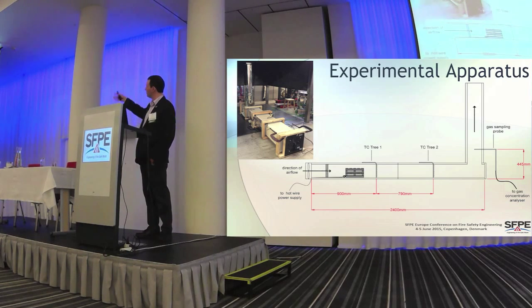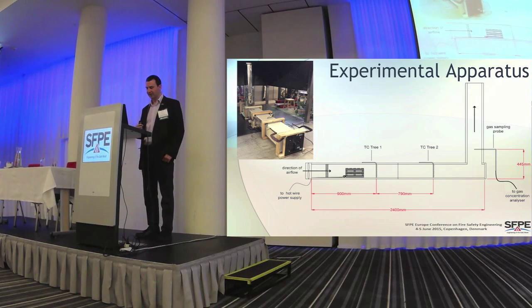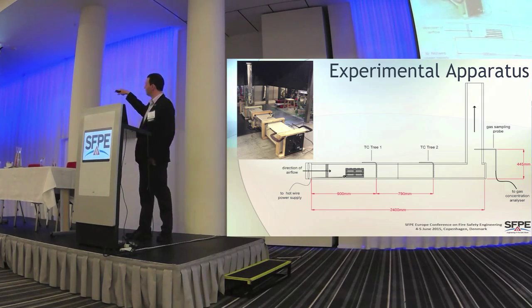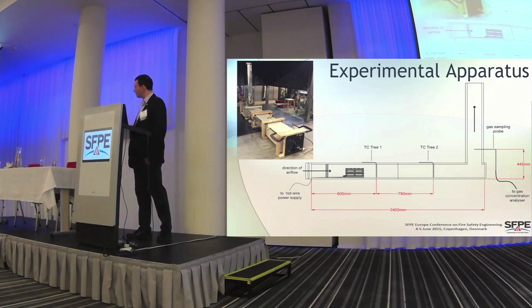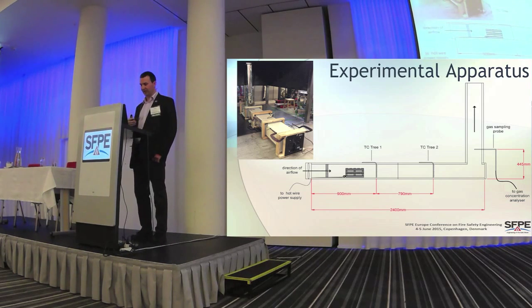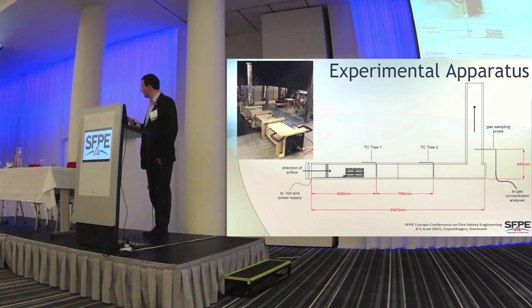We decided that we would analyse the gases flowing up the chimney because they're well mixed and you don't get any stratification effects once you're in the chimney. It should all be well mixed together. So if we record an oxygen concentration in the ducts, that should give an idea of the average oxygen concentration that's been flowing downstream of the fire location.